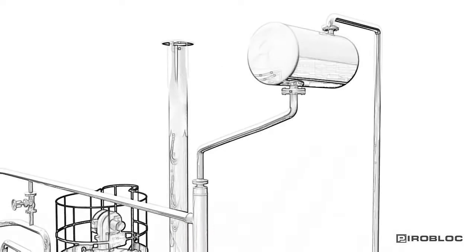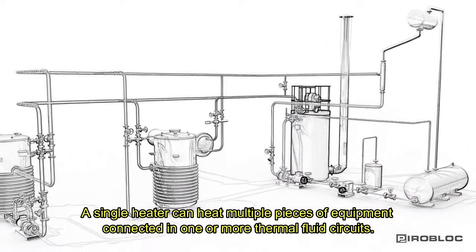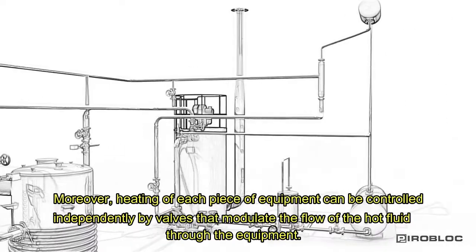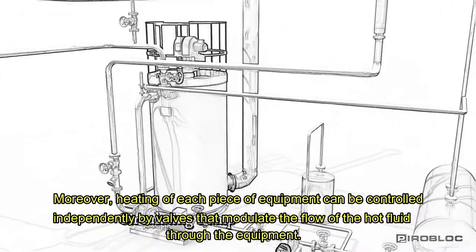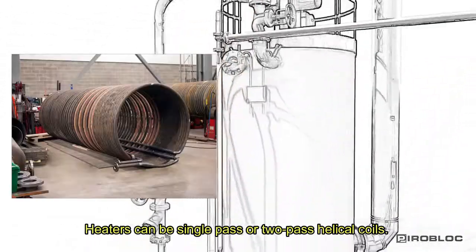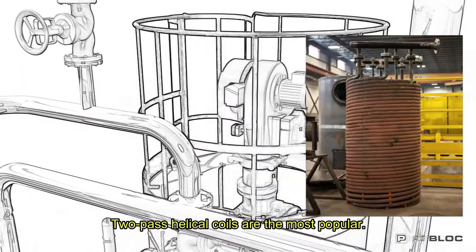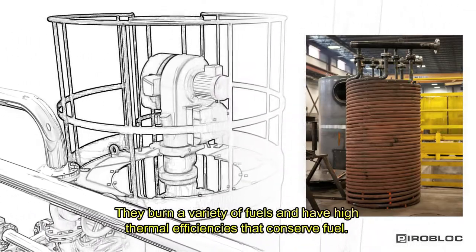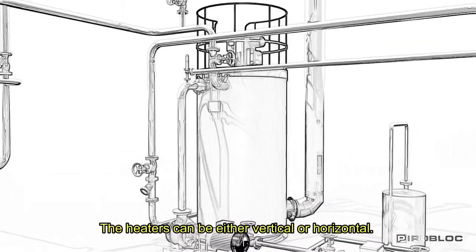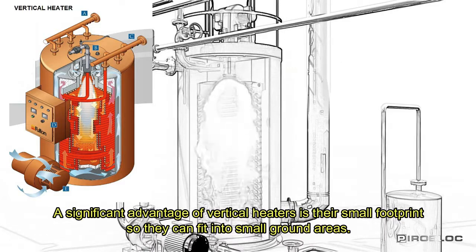Thermal fluid heater. A single heater can heat multiple pieces of equipment connected in one or more thermal fluid circuits. Moreover, heating of each piece of equipment can be controlled independently by valves that modulate the flow of the hot fluid through the equipment. Heaters can be single-pass or two-pass helical coils. Two-pass helical coils are the most popular. They burn a variety of fuels and have high thermal efficiencies that conserve fuel. The heaters can be either vertical or horizontal. A significant advantage of vertical heaters is their small footprint, so they can fit into small ground areas.